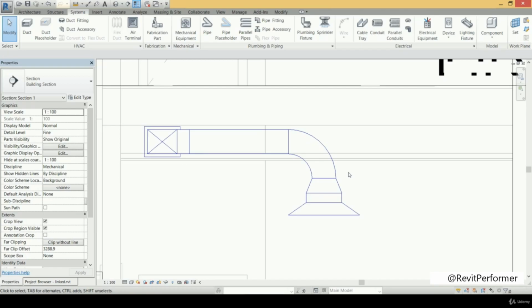But if you remember in the previous tutorial, when the vertical distance between the duct and the air terminal was narrow, in that case we were not able to draw any output to link between that branched duct and that air terminal. And in practical work, if we are facing those conditions, when the suspended ceiling is a narrow one, we cannot increase the distance. Here we have increased the distance for the air terminal. This is because we have no specific design to work on.